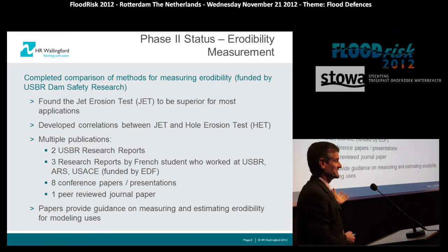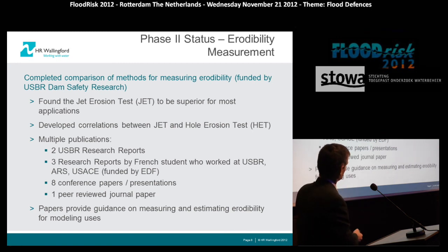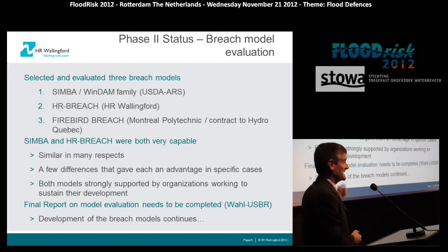And there are differences between those, so there is still ongoing debate about erodibility measurements that come out of the HET test versus the jet test and so on. And there are plenty of publications if you want to read up on that. It is important because the soil erodibility underpins any of these breach models. It dictates the rate at which the breach grows.